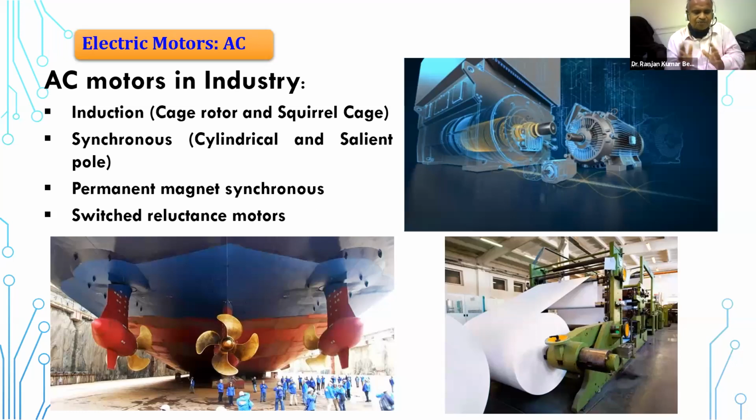So our first project was under the Young Scientist Award, for ship propulsion engine design. If you see this, it is the ship propulsion, and we designed this ship propulsion engine for the first time in our laboratory using a 5-phase machine, because in a 5-phase machine, even if one phase is out, you can run the complete unit with 4 phases.